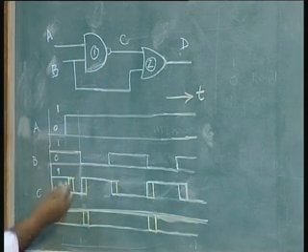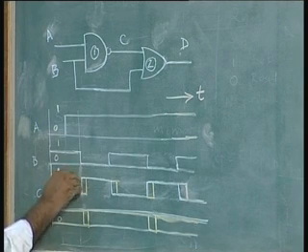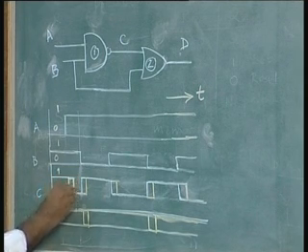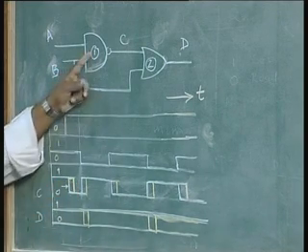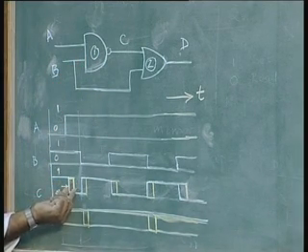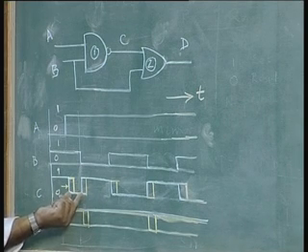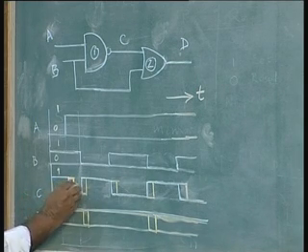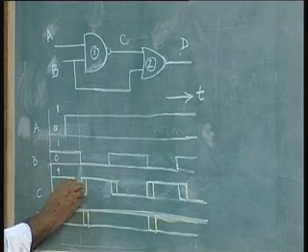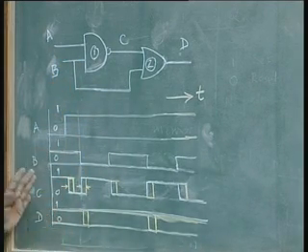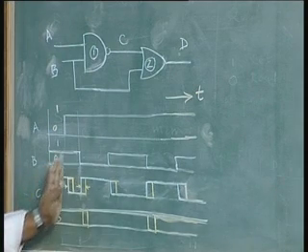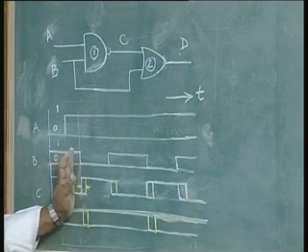That is why we use this colored chalk here, yellow. The short duration is because of the propagation delay of the gate C. Likewise, when it goes back from 0 to 1, this same propagation delay will act. So, the propagation delay of gate C will shift the output C from the original point here and here to this point and this point.